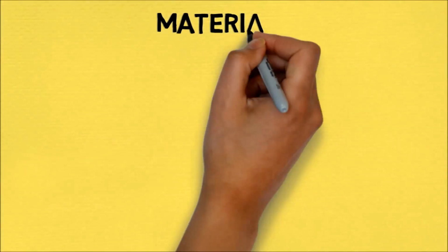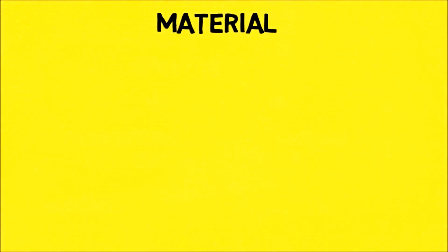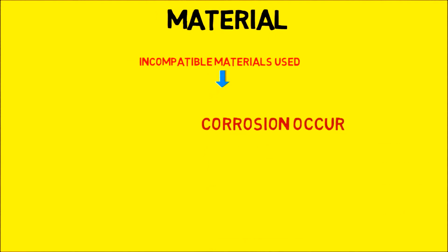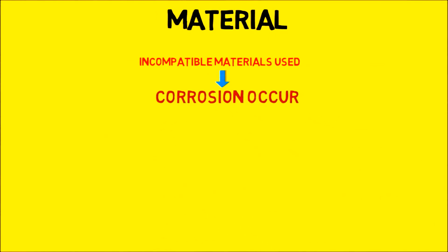One of the causes contributed by the material aspect in the boiler heat exchanger crack is the incompatible material used. Due to the material incompatibility, corrosion would occur. It is important to know the type of material used for the heat exchanger of the boiler in order to prevent failure due to corrosion. If we know the material used, even if it is incompatible or low quality, earlier prevention can be made, such as treatment of the material. There are many prevention methods in material treatment, such as surface coating, alloying, and so on.